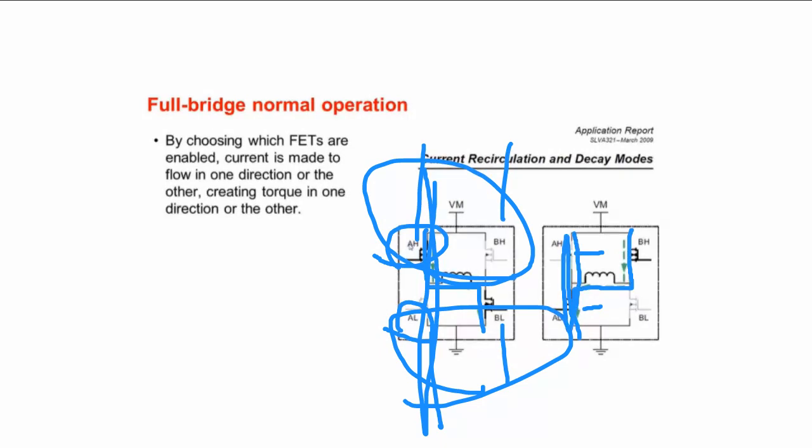If we have a short circuit, your circuit will be damaged. To prevent this, we can add dead time. For example, when the high side MOSFET goes off and the low side MOSFET goes on, we have a time in between. This time is called dead time.